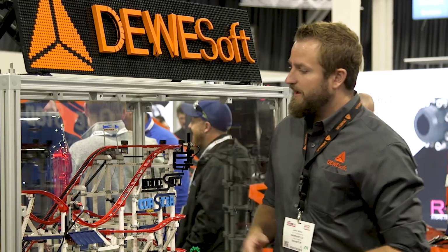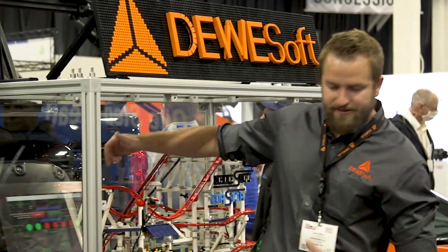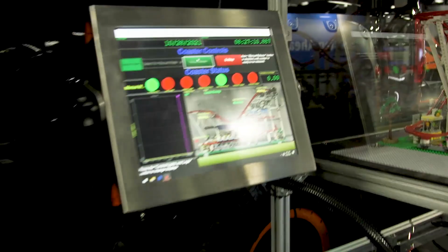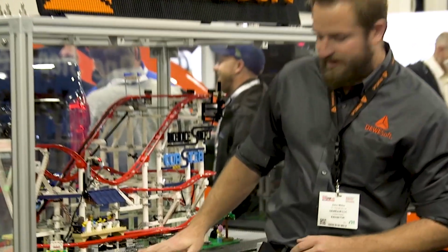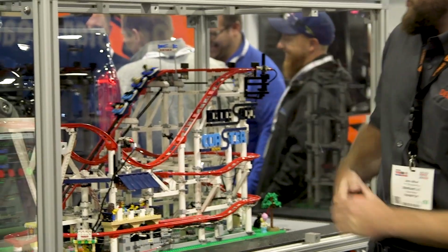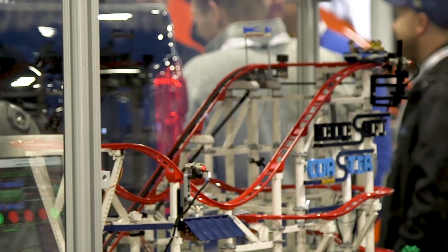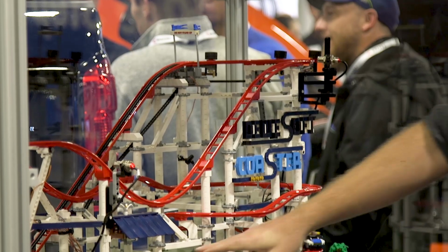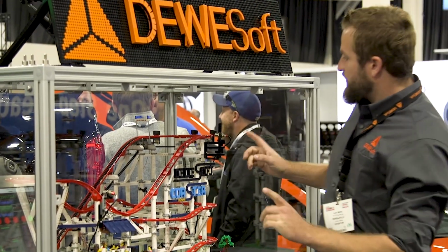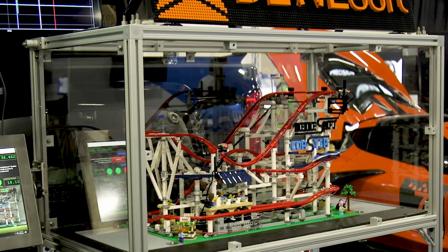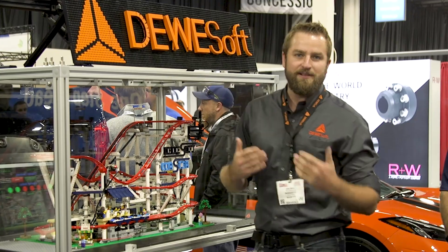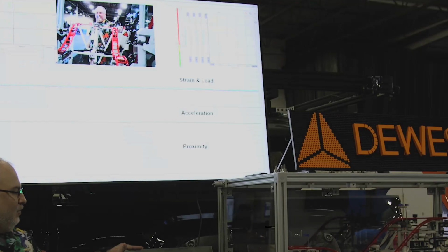Specifically, we have 4 strain gauges on various structural members, and you can nicely see it in the display. We also have 4 accelerometers, one simulating ground vibration, 2 showing sway of the structure, 1 showing the gearbox vibration, and then we also have a FUTEK load cell showing the load in the column, along with a couple of proximity sensors to show where the train is located at various times. We also have a video camera to simulate taking a snapshot of a roller coaster.